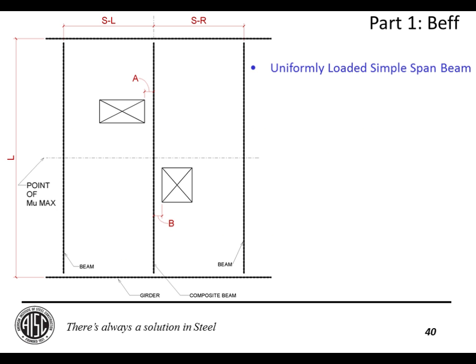But there comes a point where there are openings near your beam that you cannot ignore at all. For instance, this particular situation. Here you're looking at a plan. There's a composite beam in question here, and we have an opening that's a distance A from the center of the beam up here, and an opening that's a distance B from the center beam down here. So what I would do in practice is immediately check the beam with an effective width of A plus B. And if that beam works with that effective width, then you are finished and you can move on about your day.